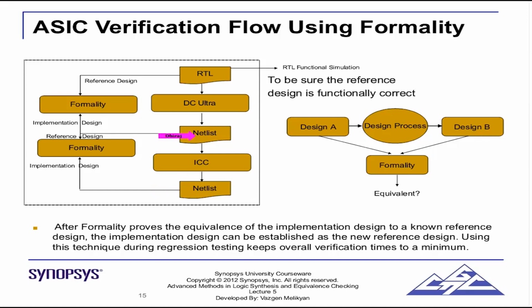You can also do Formality between the post layout netlist and RTL, but it is recommended to do the Formality as shown here. Why? Because in terms of naming conventions and structure, the synthesized netlist is closer to the post layout netlist when compared to RTL. If the two designs are structurally similar, it will take less time for Formality to verify. Since you've already verified that RTL matches the synthesized netlist, for the post layout netlist, use the gate level netlist and the synthesized netlist as golden. Don't use the RTL. You can use the RTL, but probably you will have to make more of an effort to verify the design.